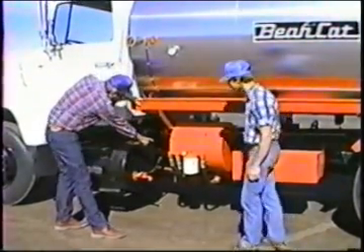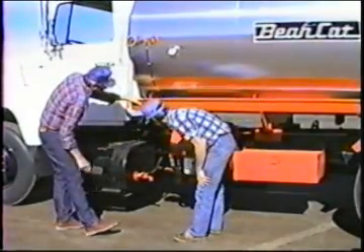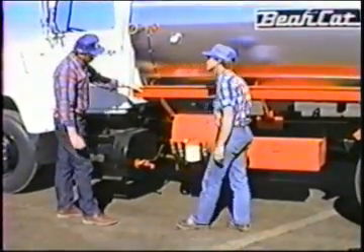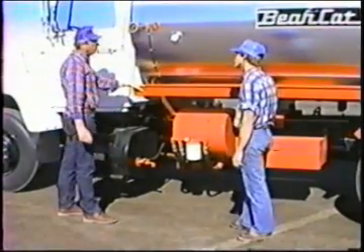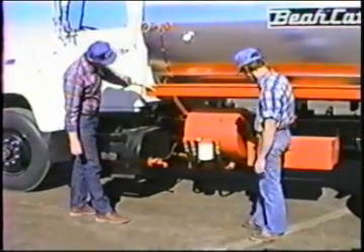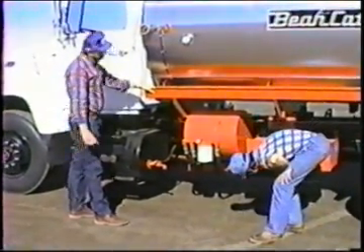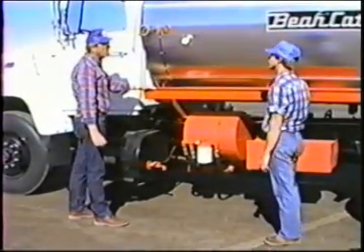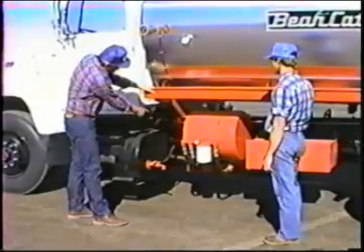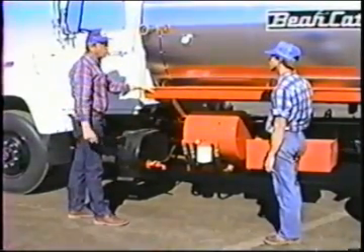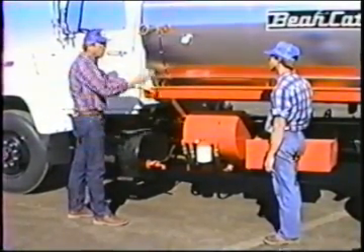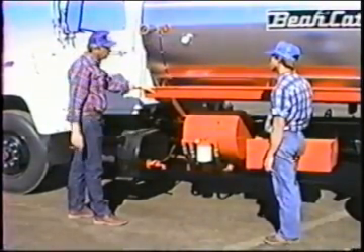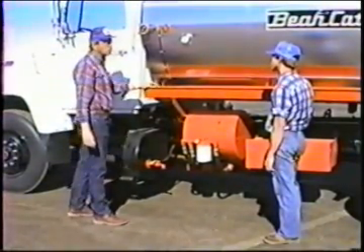Down underneath is the main hydraulic pump as well as the auxiliary hydraulic pump. They're in tandem. The auxiliary pump is plugged onto the back of the hydrostatic transmission. That is the variable volume end of the hydrostatic transmission. It's driven by a truck transmission power takeoff, or on some units it may be mounted up front off of the crankshaft, driven by the crankshaft, just like a mixer truck application.